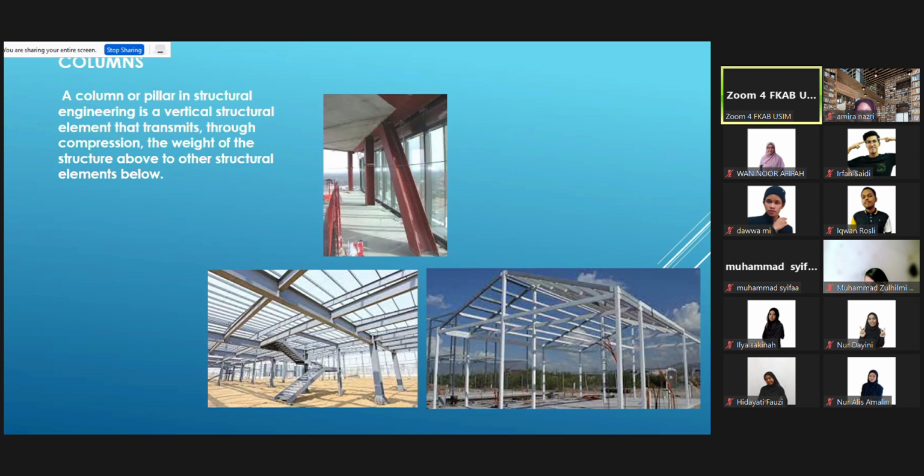Some are made of hollow section. You see the photograph on the left, right here. All this frame, the wall, the column and the beam, is all made of hollow section. It does not have to be I-beam or H-beam, not necessarily universal beam. Those are called universal beams. Round or hollow sections, not solid, can also be used as columns and also as beams.